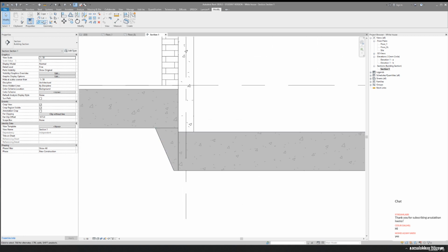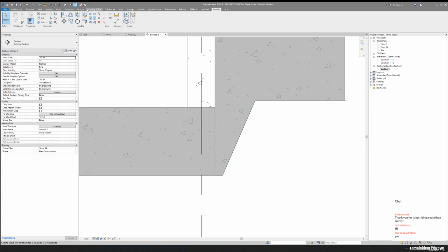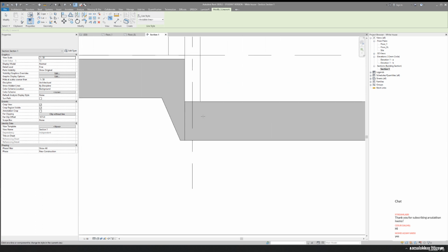Now you can of course join it. Now let's join it, and as you can see now we join. We get some problem now with the join with this and this, but not that one. Actually, how can you solve it? You can hide the line, for example. You can say I want to make an invisible line, that one and that one too, and now you don't have the line between them.